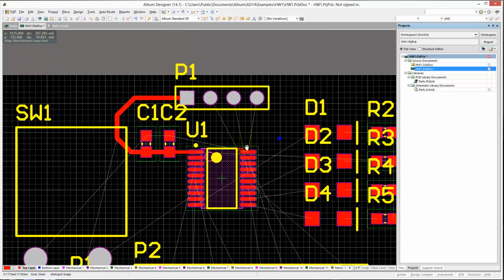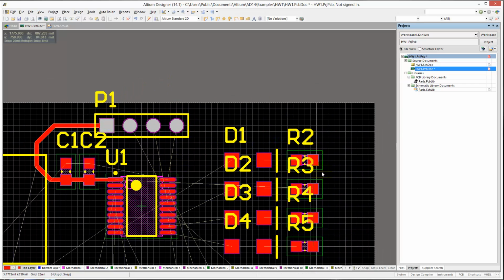All right, next step, we want to connect power to these pins over here, because these are the resistors that power the LEDs. Now, we can go and make a trace from here right over through these resistors, but the problem is these LEDs will draw a significant amount of power. As soon as they are turned on and start drawing power, the voltage will drop over here, because there is absolutely no capacitor having any kind of charge in it.